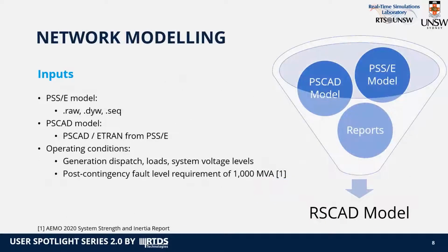The model we developed in RSCAD FX is based on PSS/E and PSCAD models and a number of reports to set, for example, the corresponding operating conditions. We used the embedded conversion tool to convert the model from PSS/E to RSCAD. Then we adjusted it and validated the network, its power flow and steady state condition by running a simulation.